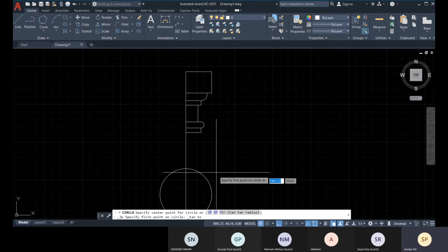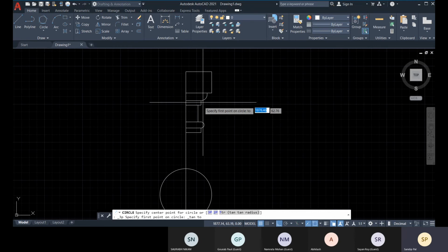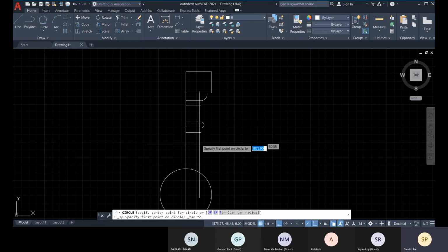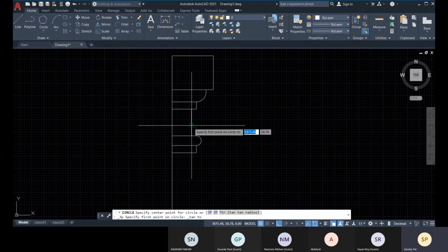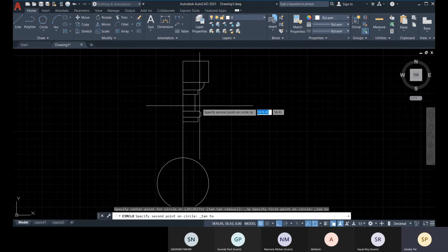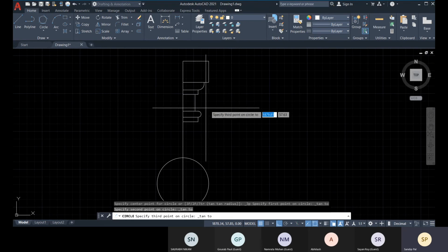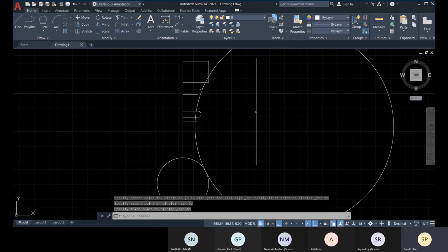And if I draw it this way, I will see that it's going like this. So then I can easily find out that these are the three tangent objects. So if I go through the drawing very well, I can get our three tangent objects. First tangent object I selected, second is selected, and I'll click on this third and it will be created.